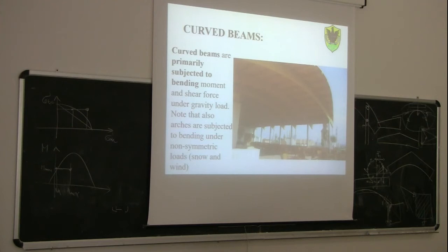So in other words, here we are almost sure that this is a curved beam, because those columns made of steel are very slender, and they are not able to act as, let's say, an external pin connection for the beam itself. Okay? Is that clear?